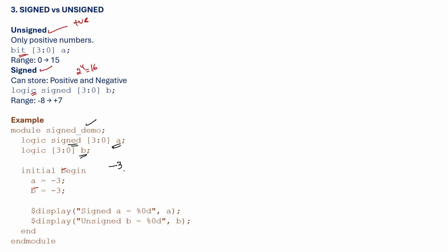See, negative means this -3 will be represented, minus means negative sign. Okay, in the MSB bit we will represent -1 here. Okay, after that 3 means 0 double 1 we can represent. Okay, but whatever the number we have, we need to get the complement of this one. Okay, 100, so 2's complement type we can represent. This is the 1's complement number. Okay, 1's complement means wherever you are having 0, that should be converted to 1, and wherever you are having 1, that should be converted to 0. Then you can ask me why this 1 is not converted.